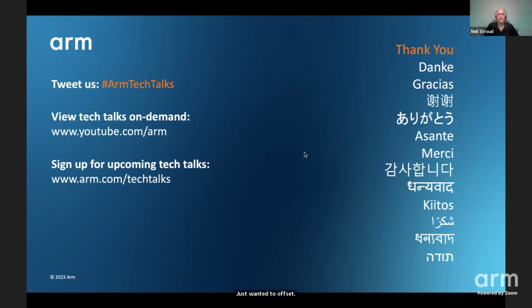I guess in that application, there's an assumption that everything that comes out of the FPGA gets rendered correctly as well. The display may have its own test mechanisms, its own periodic testing to check that once you come out of the FPGA, nothing's gone awry between there and putting the pixels on the screen. So again, I think that's a use case specific question, depending on what the application is and how robust you need to be. At some point, you've got to make an assumption that if it's gone down the wire that far, then it's probably rendered correctly. But again, it's very use case specific. So you may need other mechanisms as well.